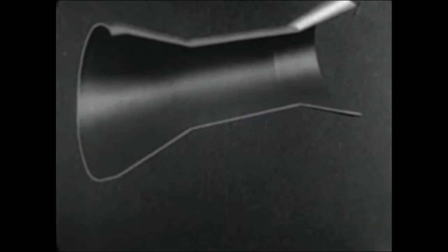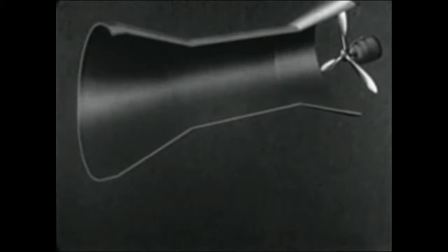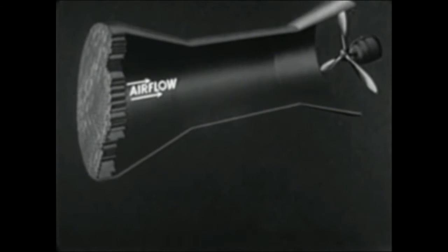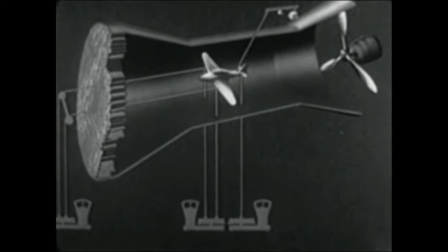A wind tunnel is a device for testing reactions on airfoils and other aerodynamic shapes. It usually consists of a large tube with a constricted throat. A propeller produces airflow, and a honeycomb arrangement is placed at one end to ensure straight airflow. When lift and drag of an airfoil are to be measured, the model is placed in the chamber and supported by wires.